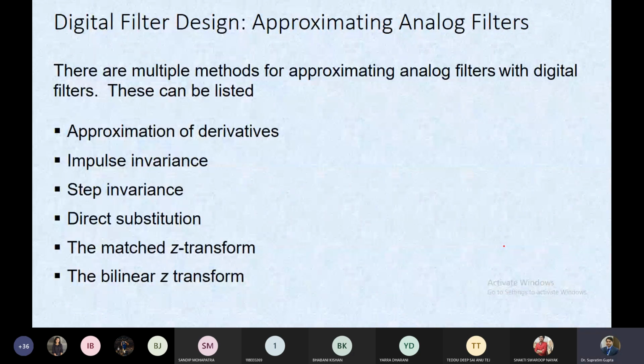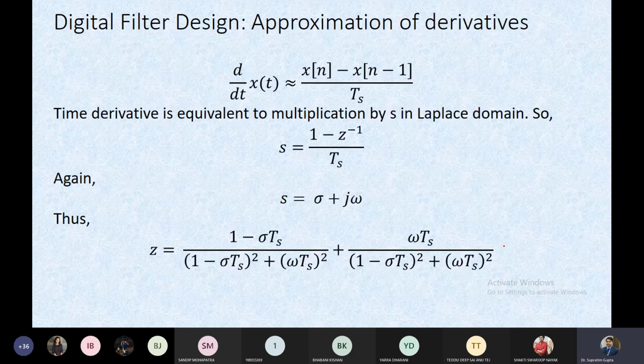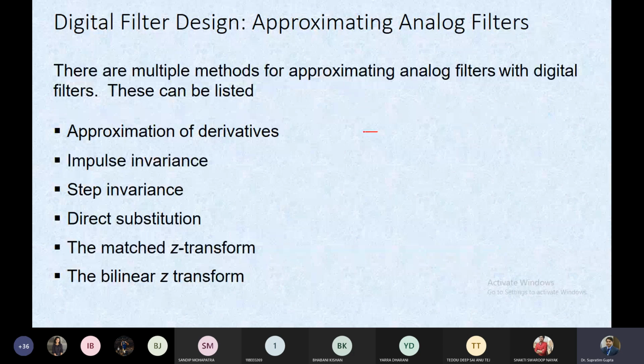Now, while we go for designing an IIR filter, IIR means the infinite impulse response. We actually include the past values of the output too. So that means we can vary this k from 1 to m minus 1 or so, and we use this a_k y[n minus k], and this will be subtracted. So that is the general model we have shown earlier.